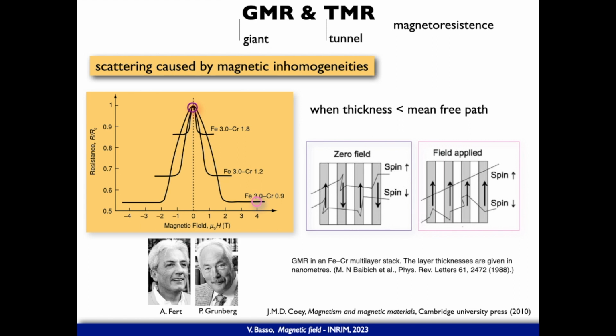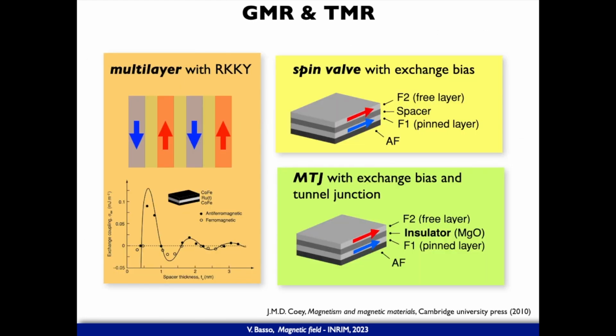These layers have to be of very small thickness, so we are in the nanometer range. But it's possible to make alternations between ferromagnets, for example iron, and a metal like chromium, and to make systems like that. The principle discovered by Peter Grünberg was then taken to a different level by engineering all these effects, by using different materials, by using just two ferromagnetic layers instead of many, or by changing the spacer between the two from a metal to an insulator, thus exploiting tunnel magnetoresistance.